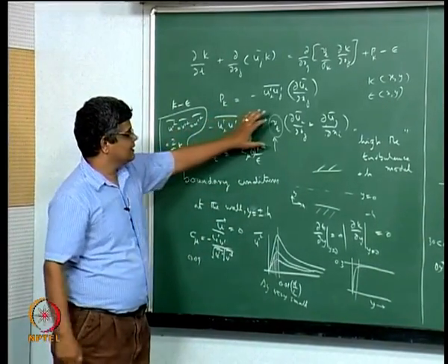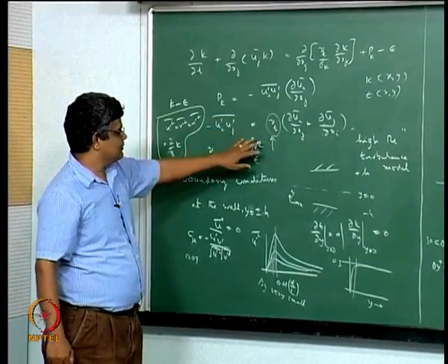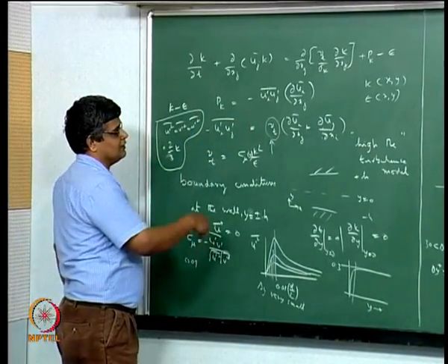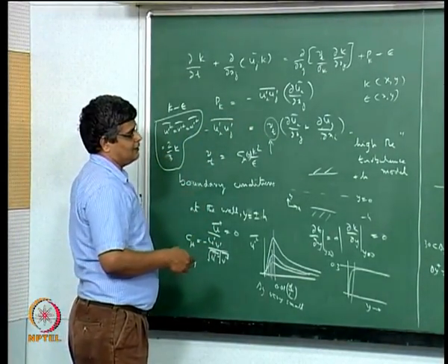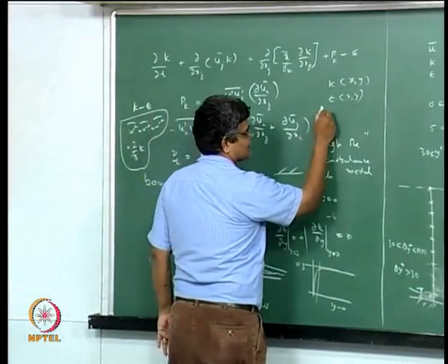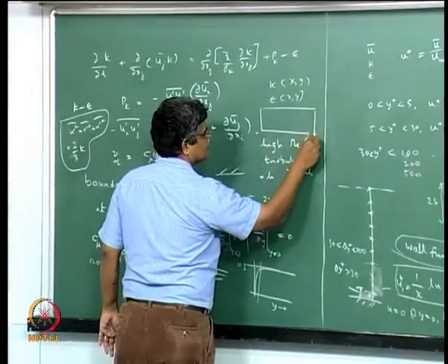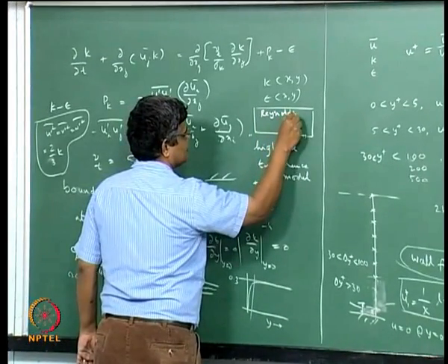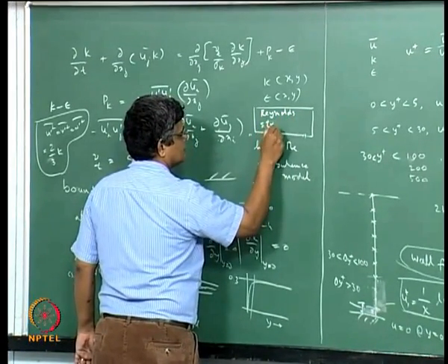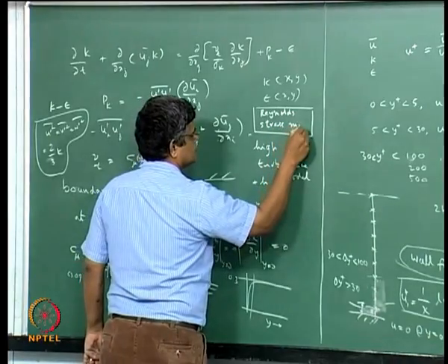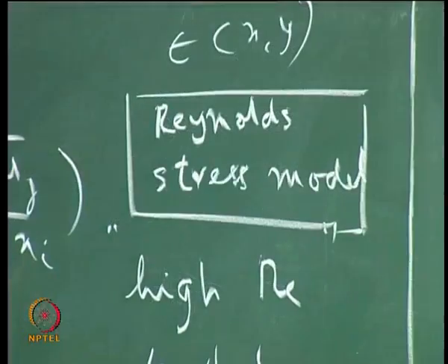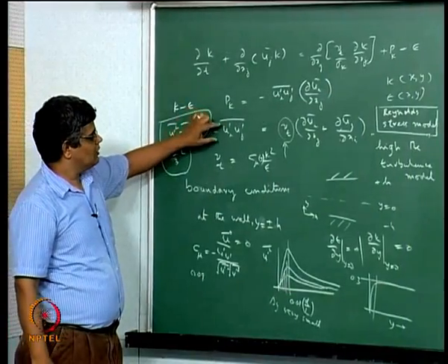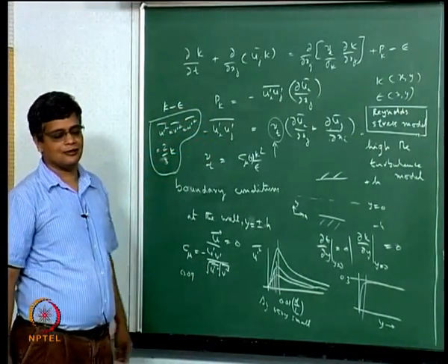And to represent the general anisotropy and the response of different turbulence stresses to an arbitrary force field, we have the so called Reynolds stress model, in which a separate transport equation is solved for each of the 6 Reynolds stresses.